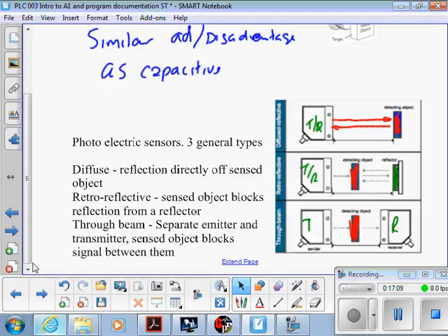Okay, with the plastic bottle thing, the issue is around how well it can sense clear plastic, in terms of the fact that the beam can go through the clear plastic, but you want to sense it. So there's set up sensitivity issues around that. They'll all work really well with a nice opaque colour block coming in front of them, but when that's something that can actually allow some light to go through, they're a little bit more tricky to set up.